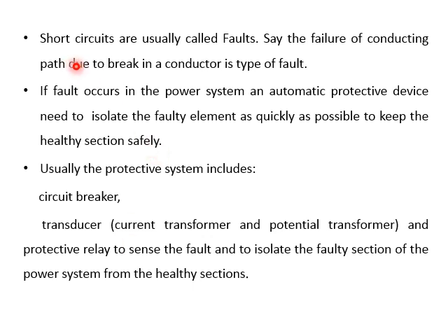Short circuits are usually called faults. Say, the failure of the connecting path due to a break in the conductor is a type of fault. If a fault occurs in a power system, an automatic protective device needs to isolate the faulty element as quickly as possible to keep the healthy section safe.